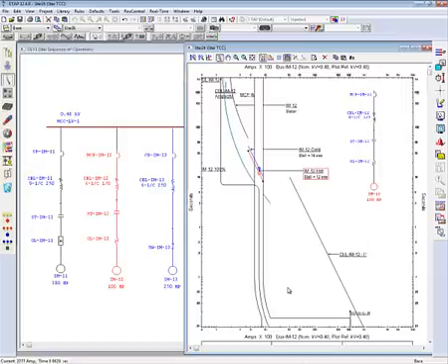Once we have all the associated curves, we want to review the protection scheme. If you look at the MCP, you will find that the MCP is actually lying on top of the LRC section of the motor starting curve, which is an indication that if you try to start this motor with the MCP in series, you won't be able to start the motor.